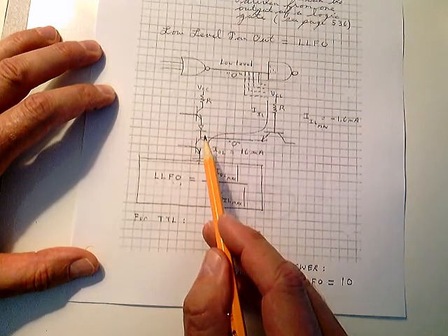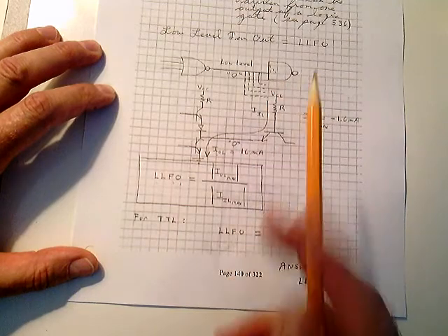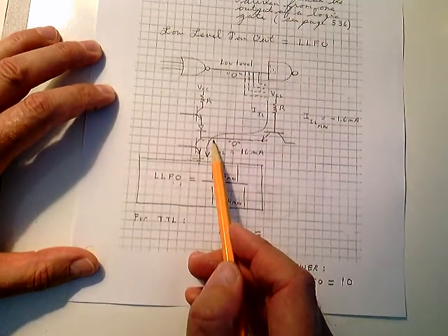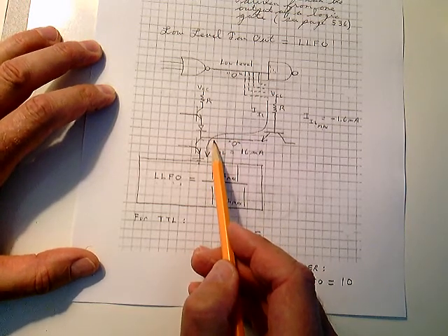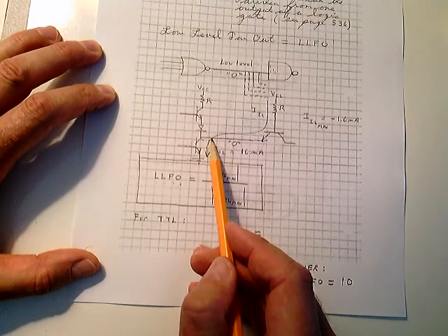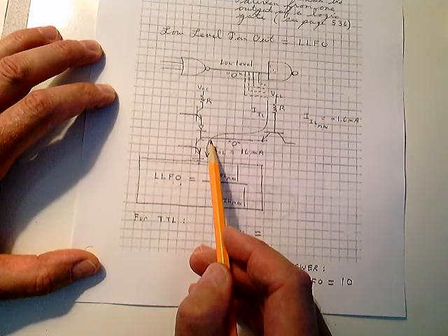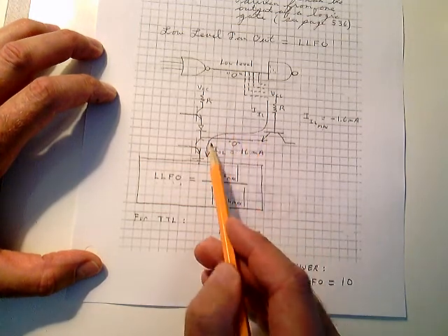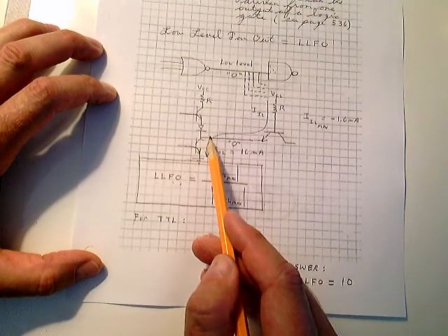You're cutting into your noise margin. So you might be able to drive 15 different circuits, but your noise margin suffers because VOL max is not 0.4 anymore. It'll go to 0.45 and 0.5 and 0.6, and you're cutting into your noise margin. And when you throw enough currents down through there and it builds this voltage up to 0.8, you don't have any noise margin at all.